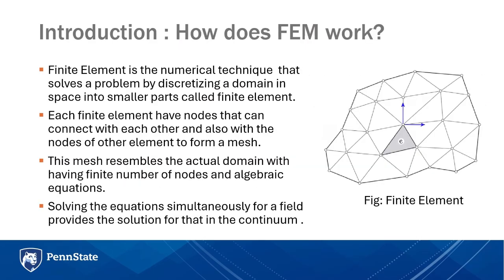As the core idea of XFEM is taken from FEM, we must know the working principle of FEM. FEM actually solves problems by discretizing a domain in space into smaller parts. These smaller parts are often called finite elements, like the shaded portion in the figure. Each finite element has a finite number of nodes that can be connected with each other and also with the nodes of the other elements to form a mesh. Each element follows the governing equations, and solving the equations formed by all the elements gives the solution of a particular problem.